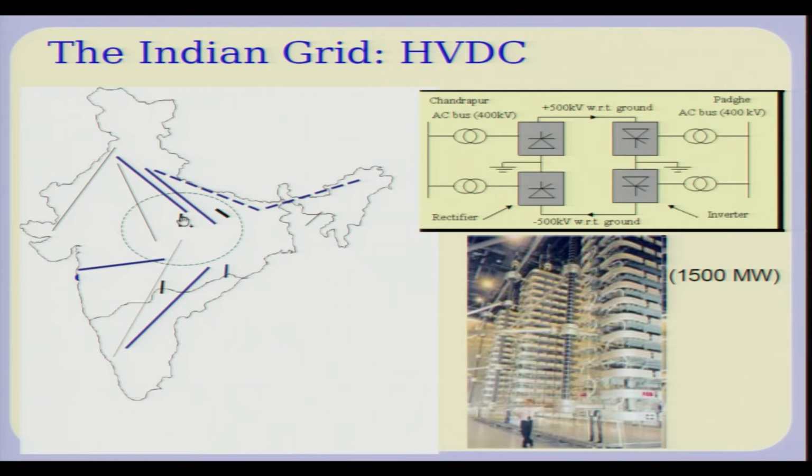Now, these smaller links here are remnants of the past. These are small asynchronous HVDC links which were present when the system was not synchronized. Now, they are in the system, they are effectively like controllable devices, but they no longer function as asynchronous links, because there are now parallel AC paths in the system. So, the main aspect now is how do you securely operate and control a power system.